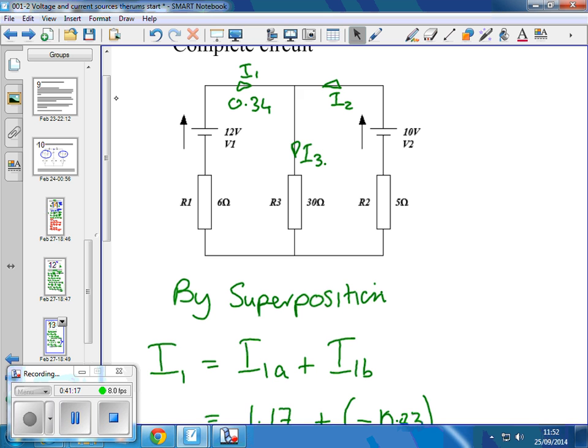You could think about your battery discharging as being a way of modelling that, as it discharges, effectively its internal resistance is getting higher. And therefore, you're dropping more voltage within the battery, and the terminal voltage gradually reduces. Eventually your device gets to a point where it senses the voltage is below a certain point and it turns off.